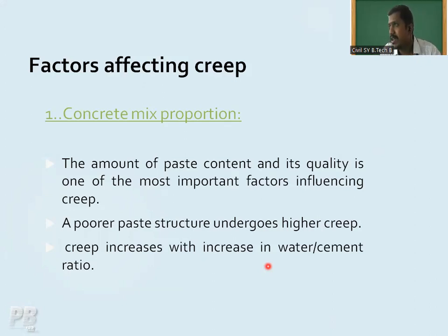If you start concreting like that, that concrete becomes highly workable. You have to check for which portion you are going to use that concrete, maybe for heavily reinforced structure, maybe for lightly reinforced structures. For which structures you are going to use it, and then you can decide the required water to cement ratio for design purposes.